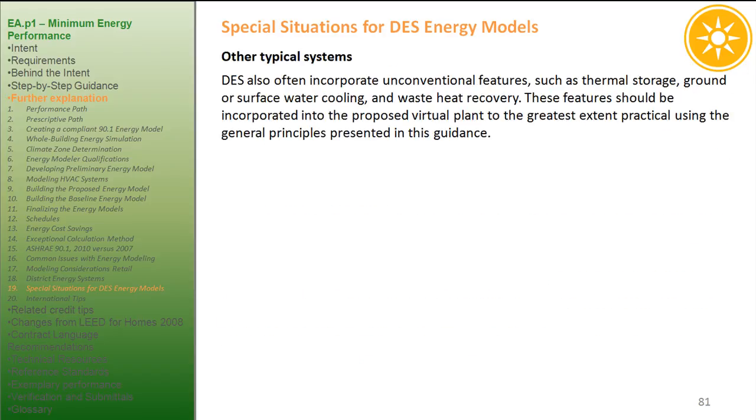Other atypical systems. DES also often incorporate unconventional features, such as thermal storage, ground or surface water cooling, and waste heat recovery. These features should be incorporated into the proposed virtual plant to the greatest extent practical using the general principles presented in this guidance.